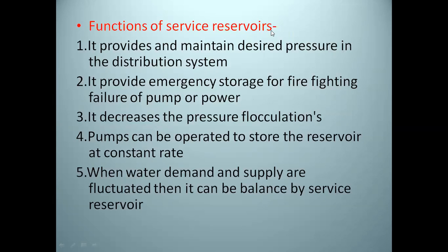After that, the next point is the functions of service reservoirs. Now see what are the functions of service reservoirs. First function is it provides and maintains the desired pressure in the distribution system. Then it provides emergency storage for fire fighting, failure of pump or power. The service reservoir stores the water, and this water is used for emergencies in the case of firefighting, or in the case of failure of pump, or in the case of power cut off.